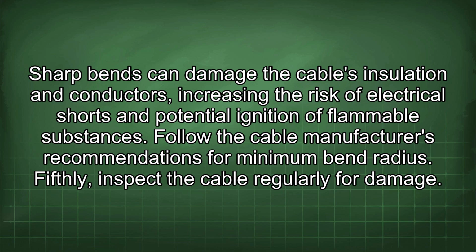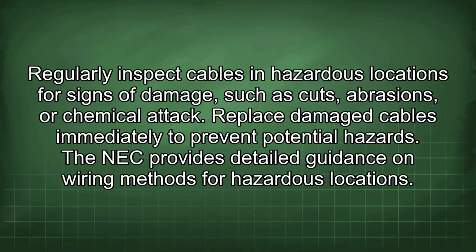Fifthly, inspect the cable regularly for damage. Regularly inspect cables in hazardous locations for signs of damage such as cuts, abrasions, or chemical attack. Replace damaged cables immediately to prevent potential hazards.